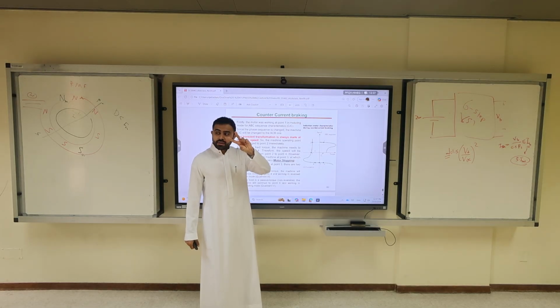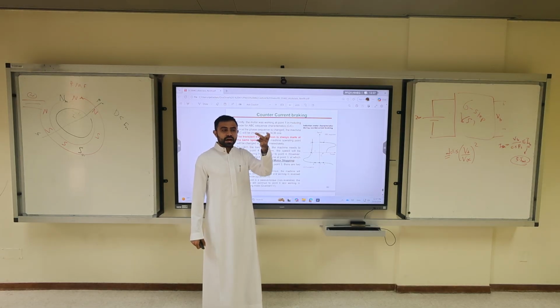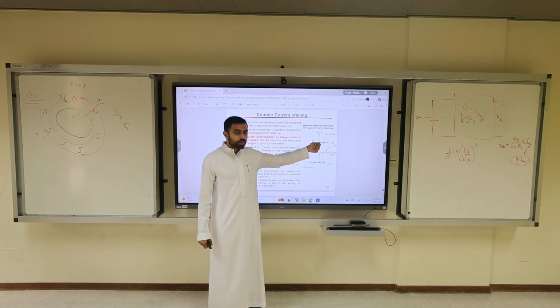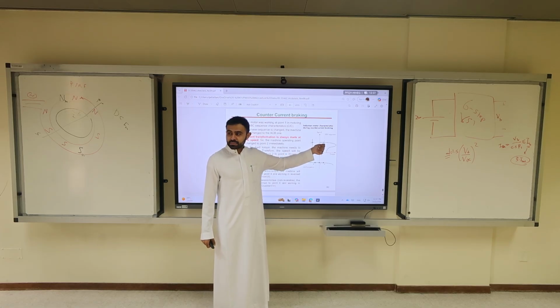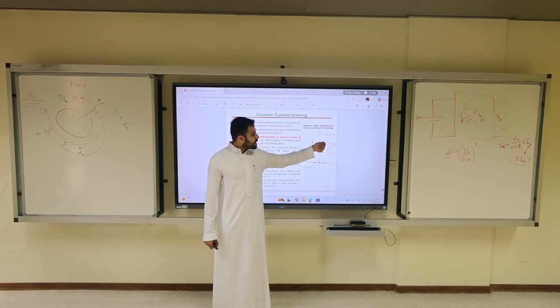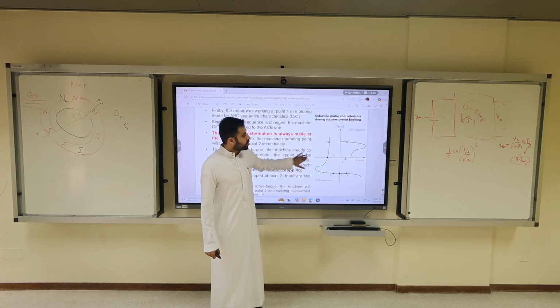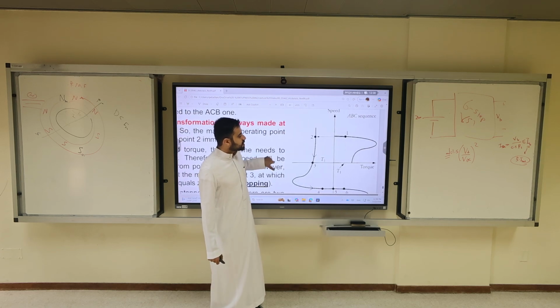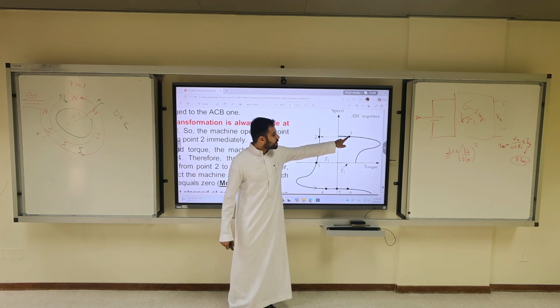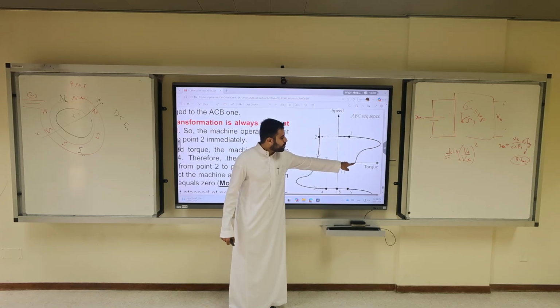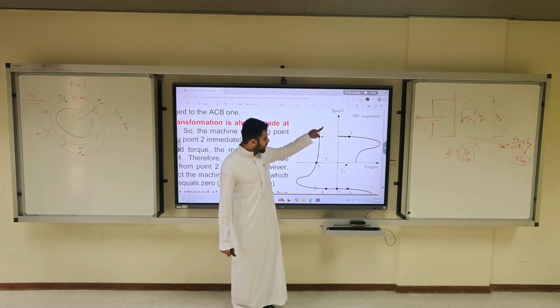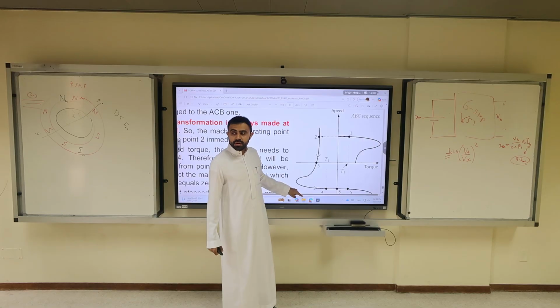Now switch to ACB. What is going to happen? We go to the plugging mode. But can you jump directly? Can you change the speed suddenly? No. We zoom in. You cannot change the speed suddenly. So now we jump from the ABC curve to the ACB curve, which is the plugging mode.